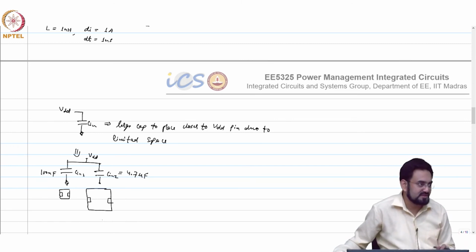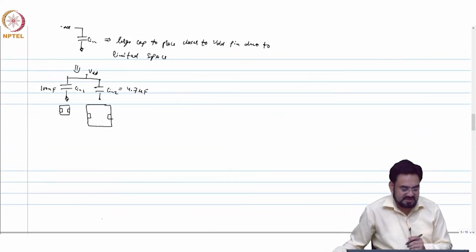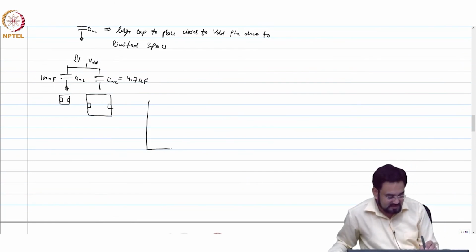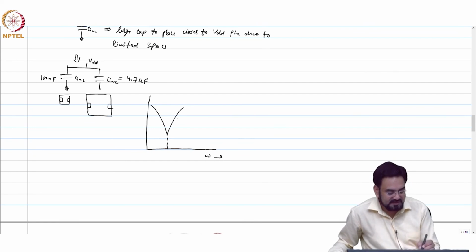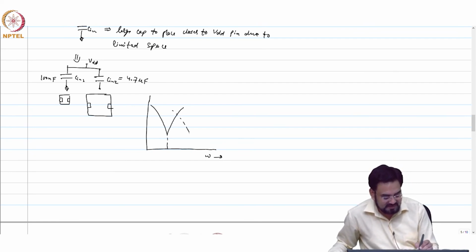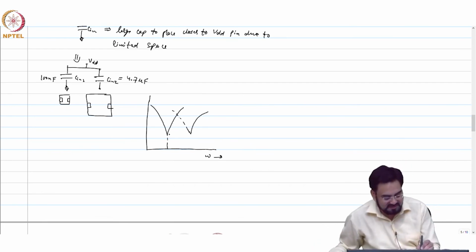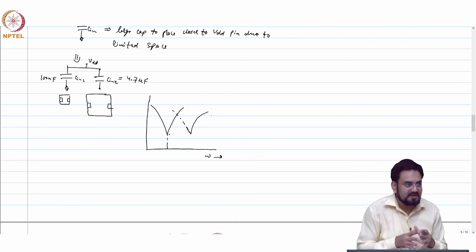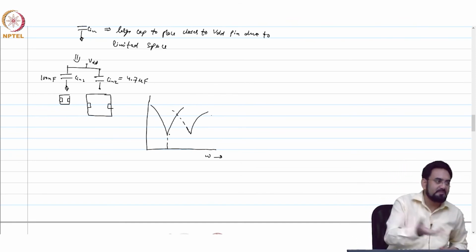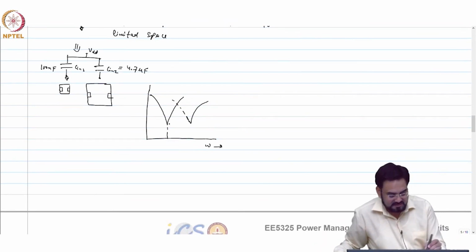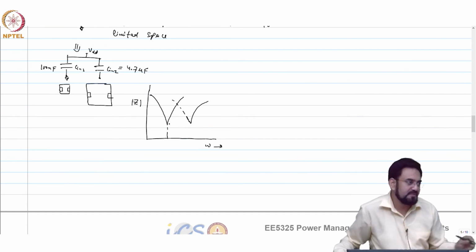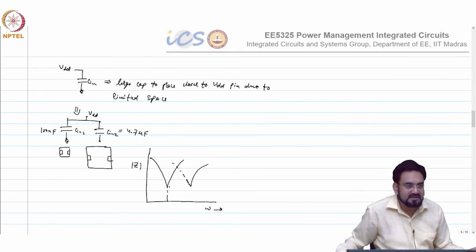So what would happen now, you will have two resonances. Okay. Two resonances means your curve will look like this, again if we have omega. Obviously the lower frequency resonance will come from the bigger cap, and then let us say my higher frequency resonance is looking like this. So effectively at higher frequency your impedance is not always increasing. The effective capacitance, if you are looking here, will look like more cap compared to the single cap. Okay. So this is a more effective way of placing the cap if there is a risk of having larger ESL.